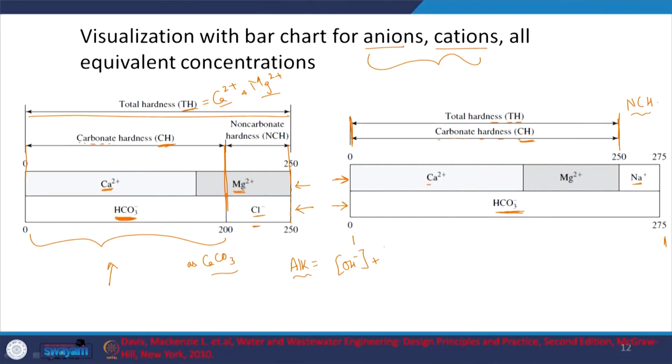So, what will it consume? It will consume H plus. What can it be neutralized by? It can be neutralized by those bases that are in that particular system. Typically, we have only the carbonate system. So, the bases are OH minus, and the carbonate system bases HCO3 minus and CO3 2 minus. Since CO3 2 minus can neutralize 2 H plus, we will have 2 equivalents here, and obviously minus H plus, let us say, right. So, this is the equation for alkalinity.